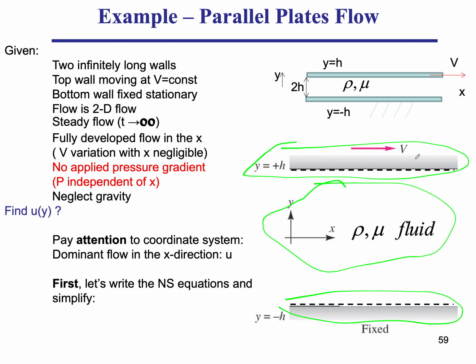Now you want to imagine that your hands are infinitely large. And the oil film is relatively thin, or actually is quite thin, for the assumptions in this problem to be valid. So we have the two walls separated by a distance 2h. Our coordinate system is y and x. X is along the direction in which the top wall is moving. That's your hand being dragged on top of your bottom hand, and this is an exaggerated view.